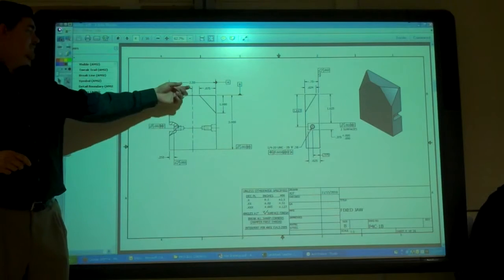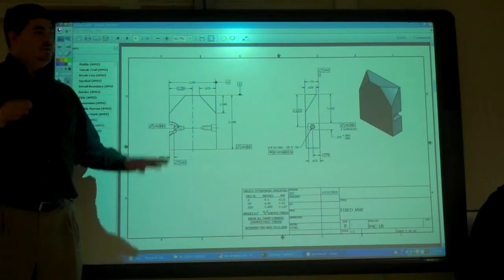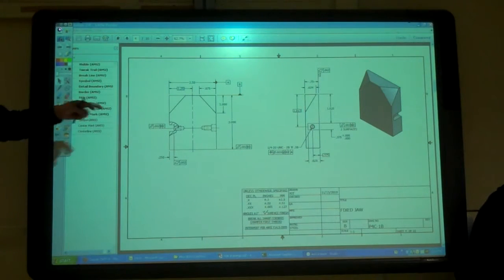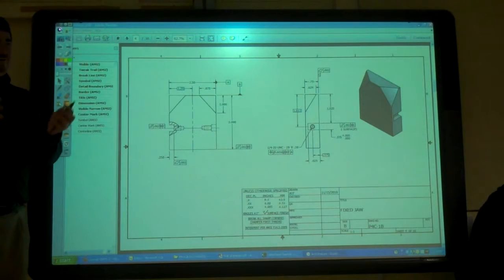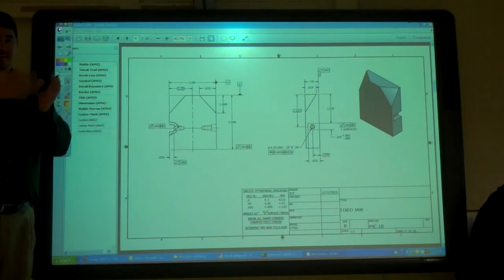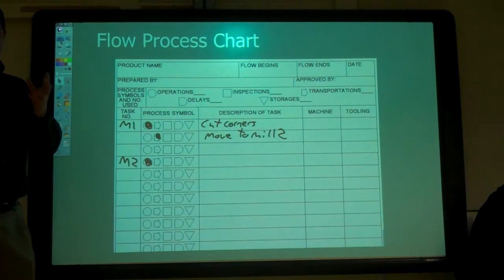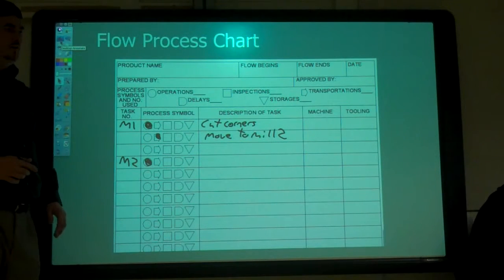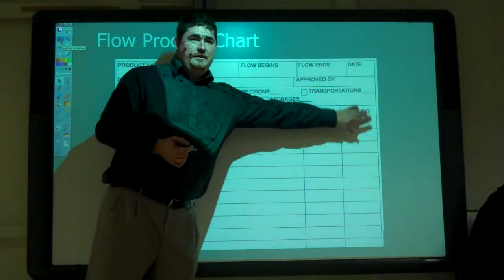So we'd want to start out of a 7/8 by 3 inch piece, a little bit longer than 3, so we can cut some material off of it, or 3 1/4, or 2 3/4, whatever your shear allowance is. Make sure you've got enough space that it's going to come out right. And the tighter the tolerances, the more material you're going to have to waste, because you can't usually start with just the raw material. So we'd put it in the machine, using the tooling that we were using, so the jig numbers.